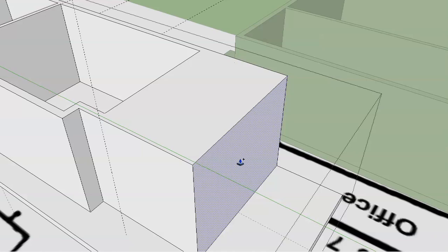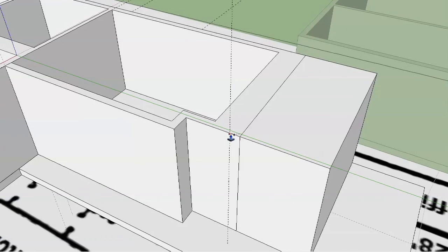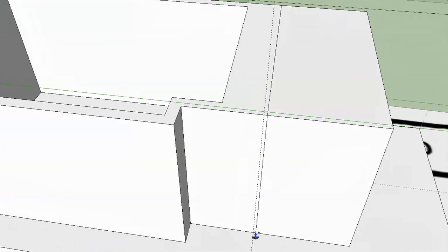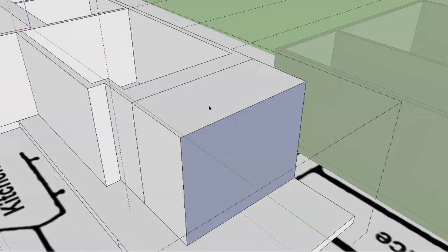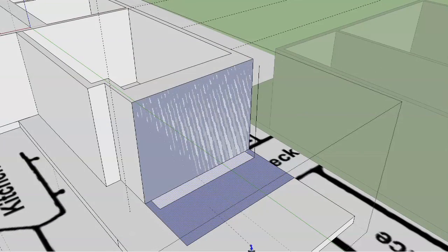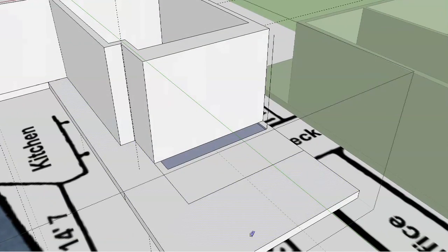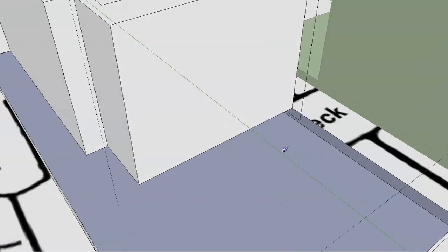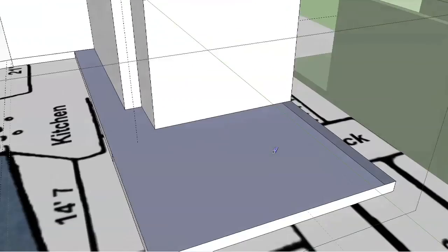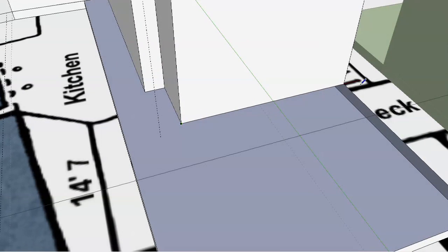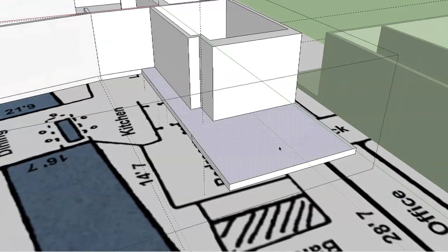When you're moving walls like this with some really complicated lines, you're going to run into this problem every now and then. But again, just like we did earlier, it's very easy to fix. We'll just use the Option key to push a copy back so that we just get some lines where we need them. Right there. That's where we want it to end. And now I can just take this wall here and push it down to the bottom and let it disappear. And you can see we've got all kinds of weird lines here because we're manipulating this house so much. So I'll just get rid of those lines and then I'll redraw one of these lines here to bring back that top face. There we go.